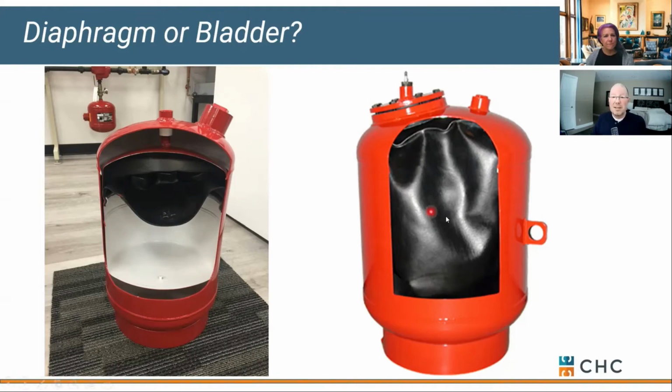So you would expect a typical expansion tank in a hospital setting to last many, many years. In a school, you're going to be cycling it more, so you're going to be on the lower end. But all you're doing is racking up cycles and stretching that rubber in the process.